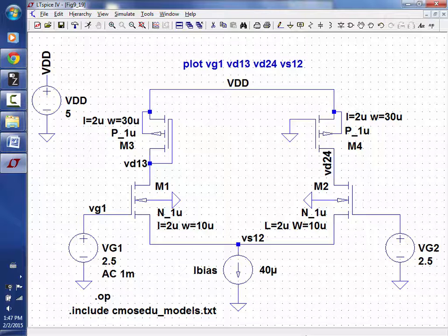And so you need to know to equalize the drain to source voltages. That is the most important thing for matching. If you don't do that, nothing matches. Okay, any questions on that? So if someone were to give you this circuit and ask why this transistor has slightly less current than this one, everybody could articulate the VGSs are exactly the same.